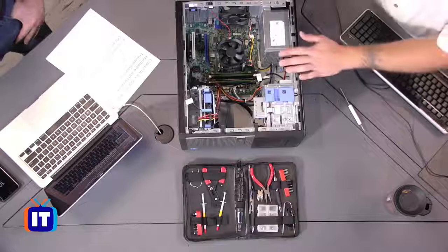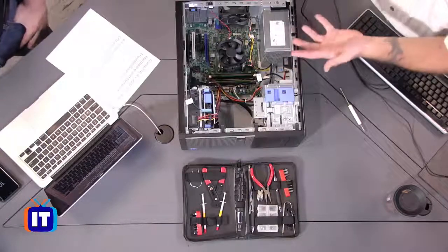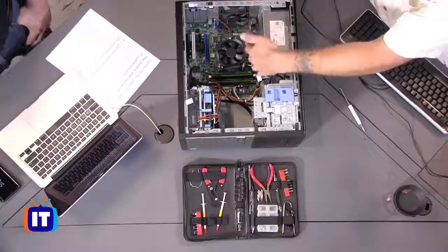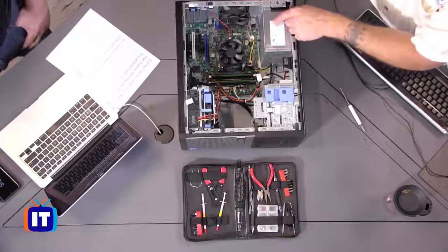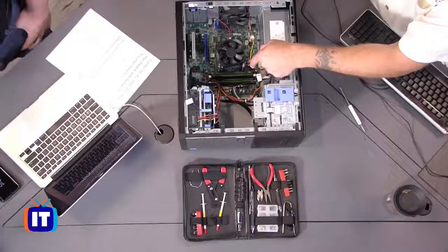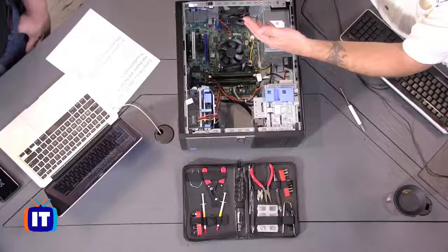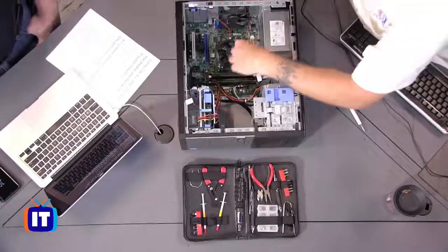So Dan, we were talking about power issues, and sometimes things don't manifest themselves as if you know that it's a power issue. I can give you one example. Let's say your CPU isn't receiving power, whether it's a rail coming off the power supply itself, or the connector, whether it's the 8-pin EPS connector or the old P4 ATX connector, if that's failed.